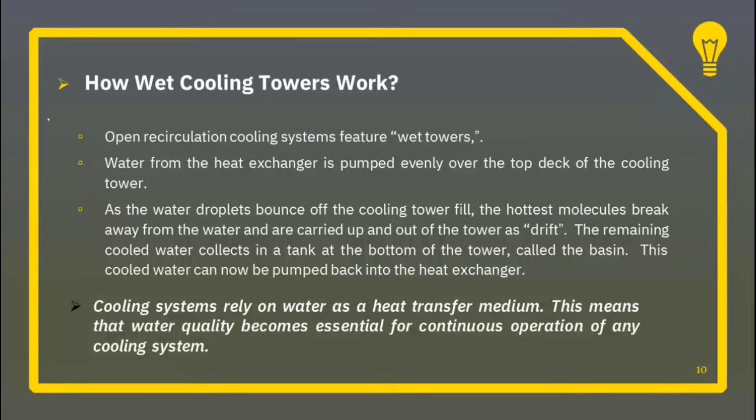As the water droplets bounce off the cooling tower fill, the hottest molecules break away from the water and are carried up and out of the tower as drift. The remaining cooled water collects in a tank at the bottom of the tower called the basin. This cooled water can now be pumped back into the heat exchanger.